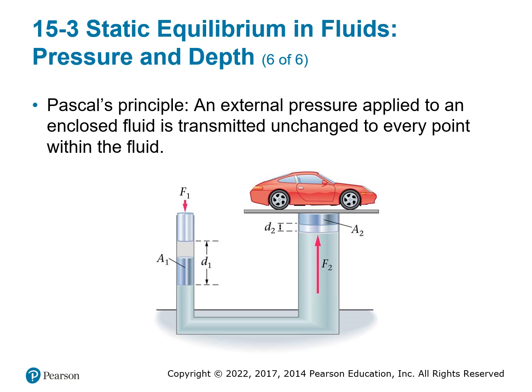We can go more into detail and call this Pascal's principle, which means that any external pressure applied to an enclosed fluid is transmitted unchanged to every point within the fluid. So kind of how a car lift works. You apply force on one side, then that pressure is going to add to the force that helps push up the car and make it lift.